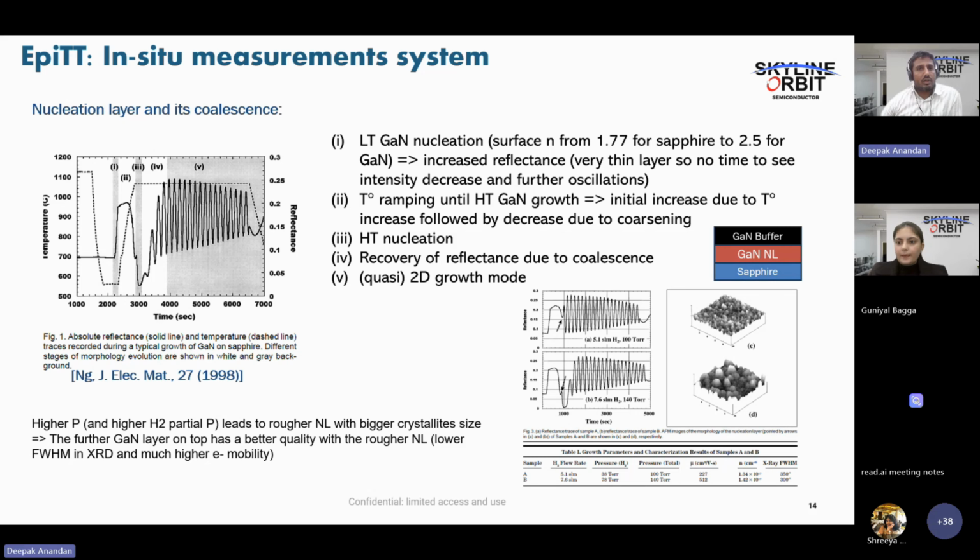For example, if you are really concerned about the 2DEG formation, or if you are really concerned about the threshold voltage, both have a trade-off, as I explained. For the gate leakage here, they are basically using two different techniques. One is Schottky contact, and another one is ohmic contact based.